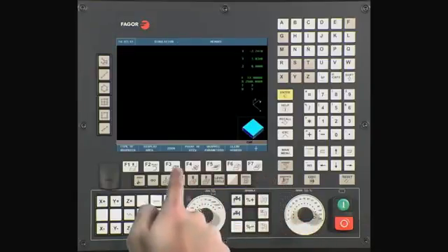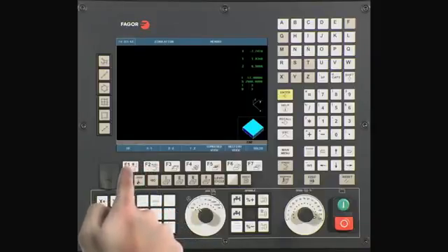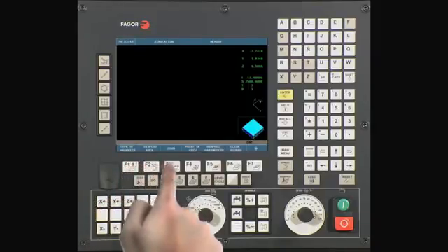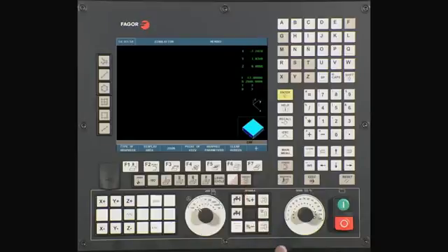Select Type of Graphics. Select 3D Graphics. If necessary, press Clear Screen to remove any unwanted graphics currently on the screen. For safety reasons, turn down the feed rate to 0. Press Cycle Start. The CNC will now ask you to turn up the feed rate. The CNC will now simulate the cycle. The process should complete with no errors.